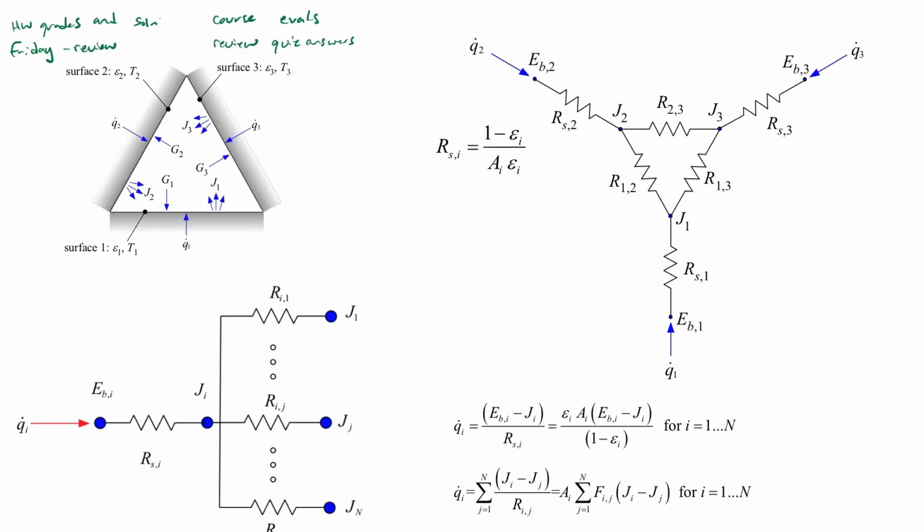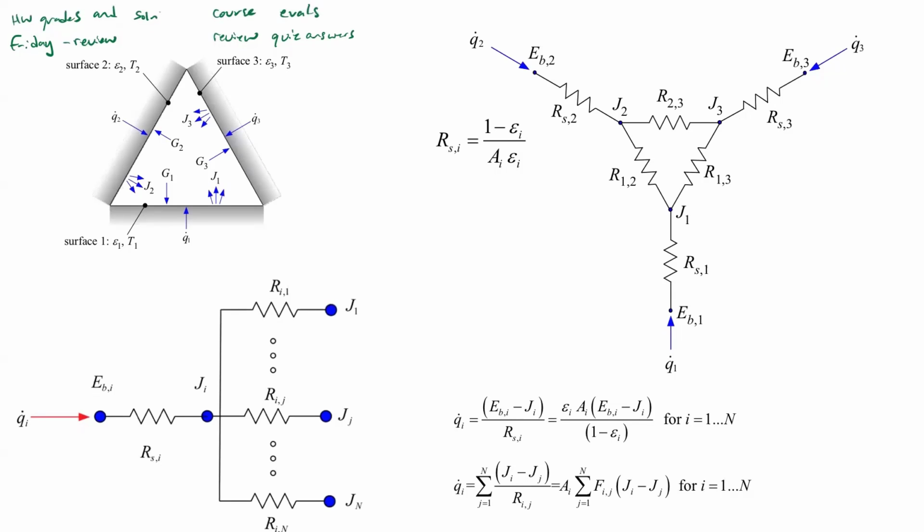So just to wrap up, we went through this last part really quickly last time. We were talking about a three-surface problem and trying to come up with a model for how radiation flows in this three-surface problem. And we decided that, okay, we can have the same kind of triangle, right? The same three-surface network that we had with just black surfaces.